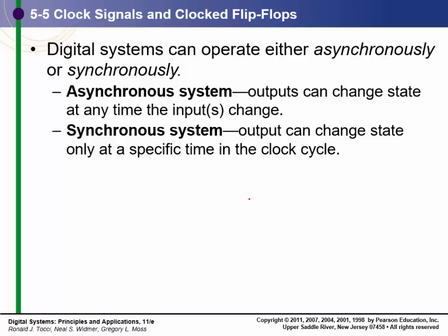The reason is propagation delays through the gates. We talked about propagation delay, where the output varies from the input by the propagation delay time. We talked about why we use look-ahead with adders, to get away from this time that things are wrong.